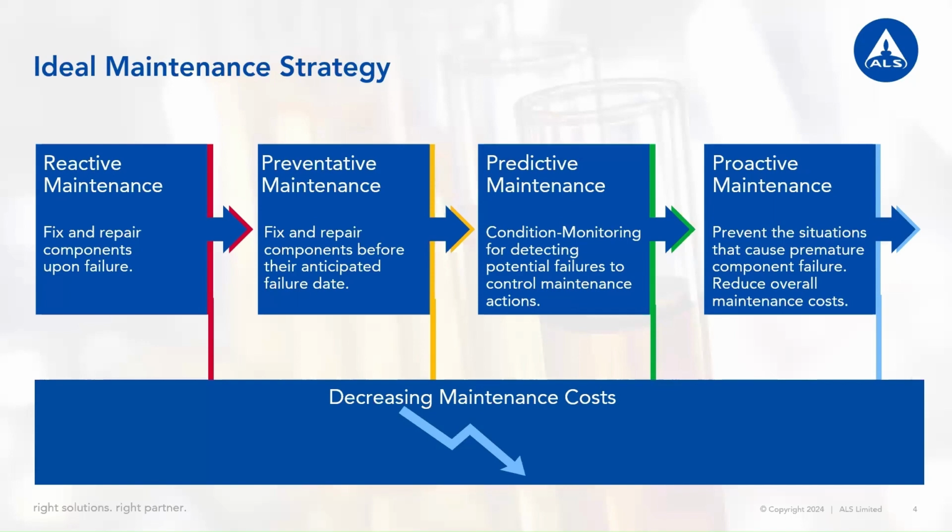Finally, proactive maintenance is the most efficient strategy when it comes to managing a maintenance department. It is predictive maintenance with the added step of making sure that no equipment fails in the same way twice. This requires continuous equipment monitoring and flexible changes made to maintenance priorities to achieve the maximum effectiveness. For a majority of equipment, this is the stage that most maintenance departments want to reach. It'll provide the lowest maintenance cost with the least amount of downtime for equipment.